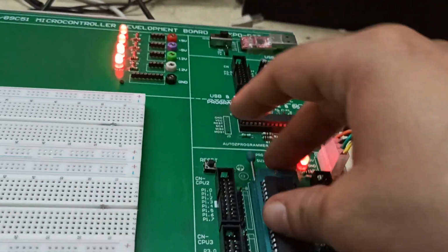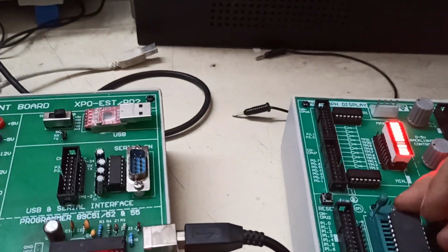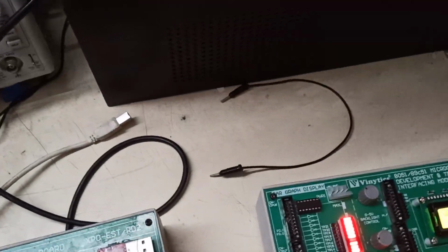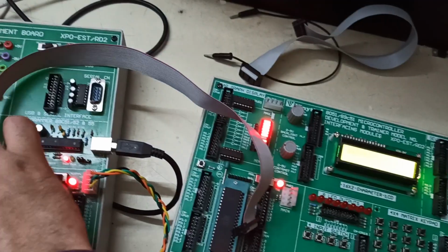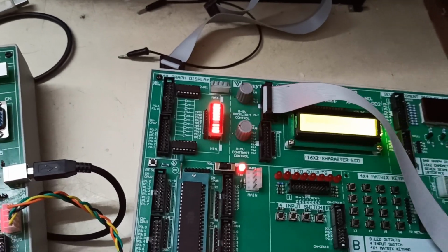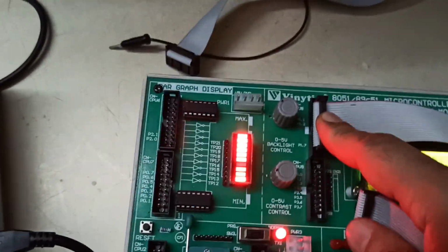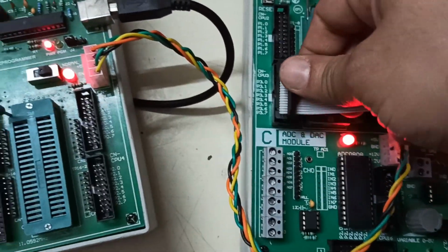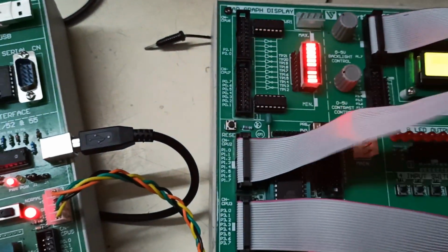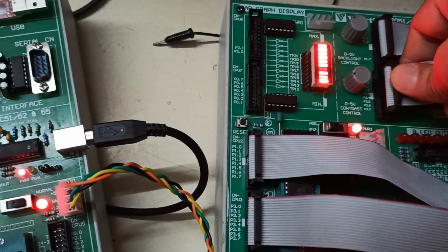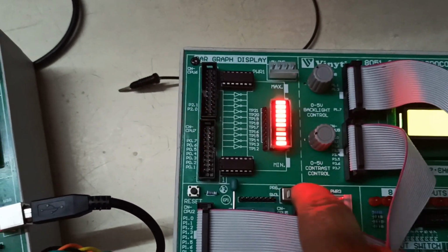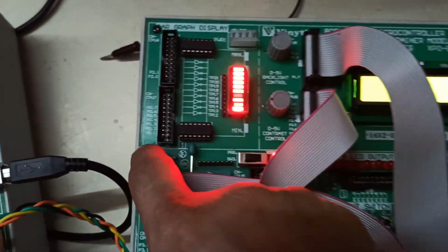Now you have to transport the IC from the socket to our programmer board, and in the programmer board, as per the manual, you have to make two connections for LCD. Every connection which I am making here right now is mentioned in the manual. This connector CPU 1 goes to CPU 3, and CPU 2 goes to the other. Now even in this, if you want to use reset, use it in the left position, that is the PRG. Press reset.